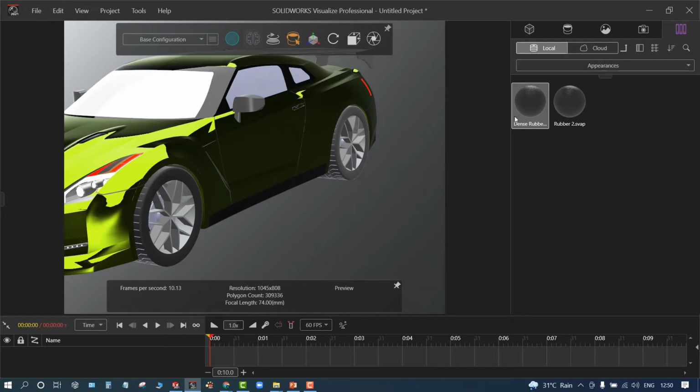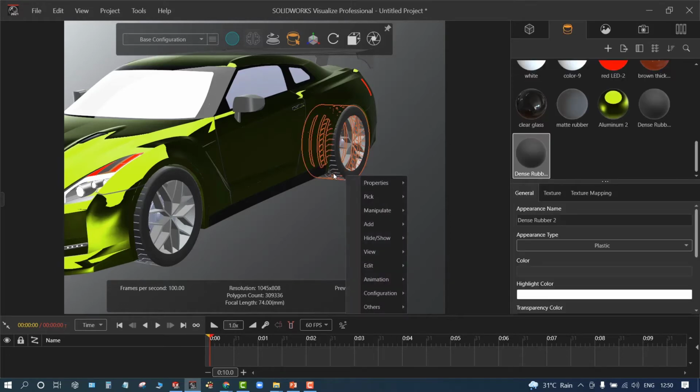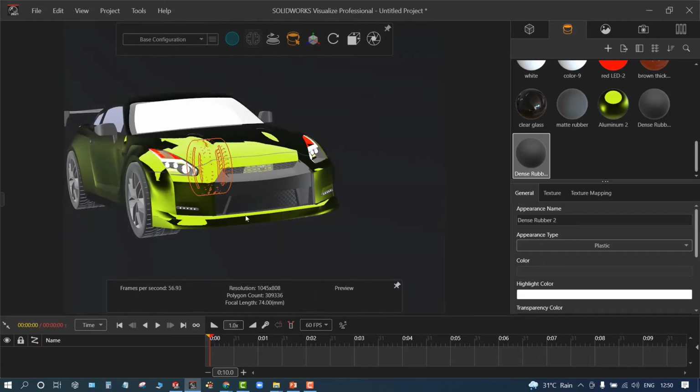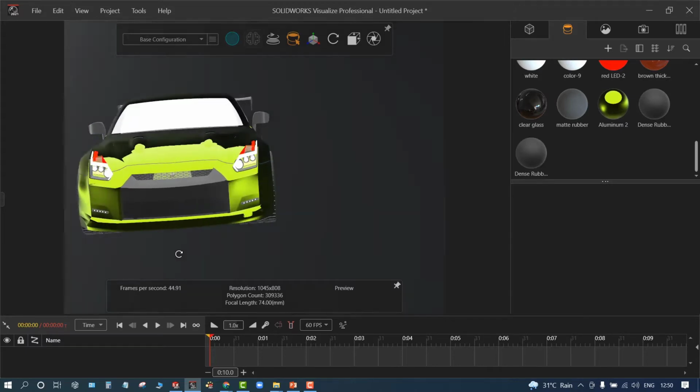And for example, if you want to utilize the same particular feature multiple times, you can hold the shift and simply select that one, and you can simply add to order by just pressing the right click in your mouse. So hold the shift, select the appearance, and left click on each and every place where you want to add it. The shortcut to apply the